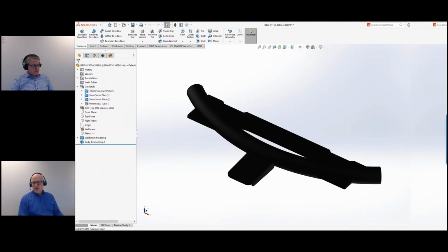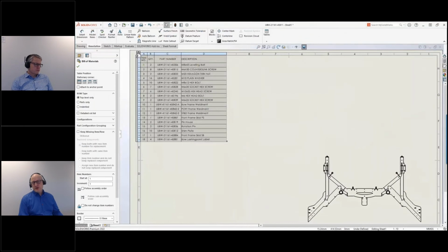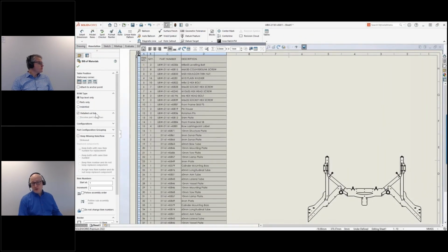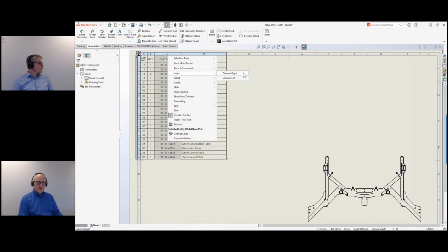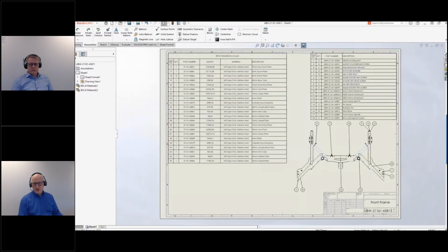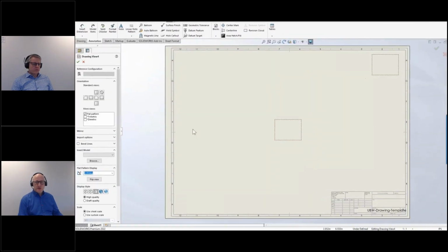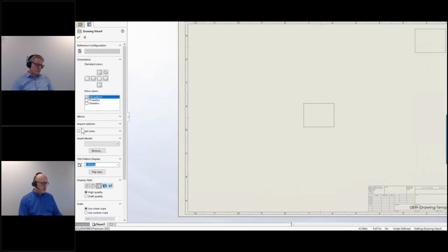Another big news for some of you is that you can now add cut list information from a weldment or a sheet metal component into any BOM type in a drawing or anywhere else that you have a BOM. Which is quite nice for those of you who work with mixed assemblies.